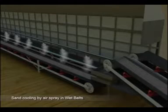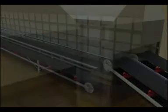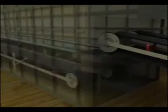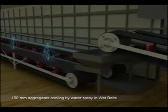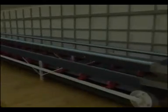The conveyors carrying aggregates of size 10 mm and sand pass through a chilled air blast, while larger aggregates pass through wet belts with chilled water spray with temperature of 2 degrees centigrade. To allow the extended time of travel for the aggregates in the wet belt, the conveyors move at a much lower speed. The temperature inside the wet belt is maintained at 4 degrees centigrade.